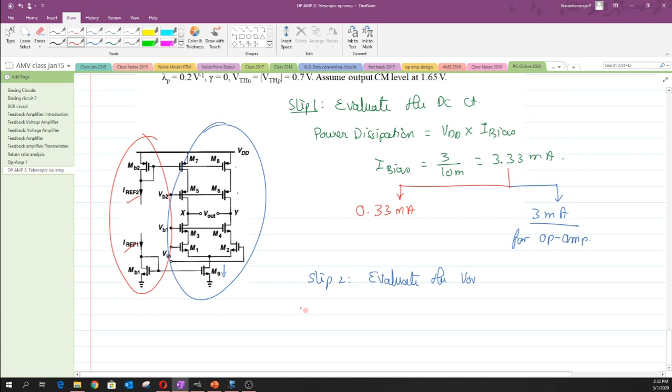We know that since it's a differential output swing, the expression of output swing can be written as 2 into VO max. So again I will plug in this expression directly. VO max is nothing but VDD minus VOV 7,8 minus VOV 5,6 minus the VO minimum swing, which is again these VOVs, written as VOV 3 minus VOV 1 minus the VOV of 9.